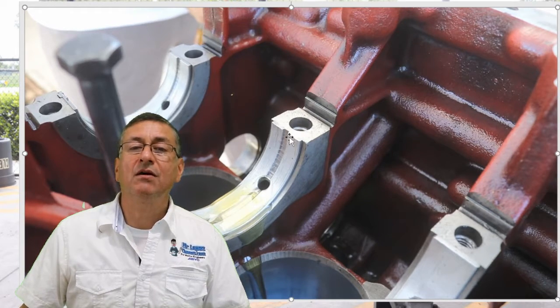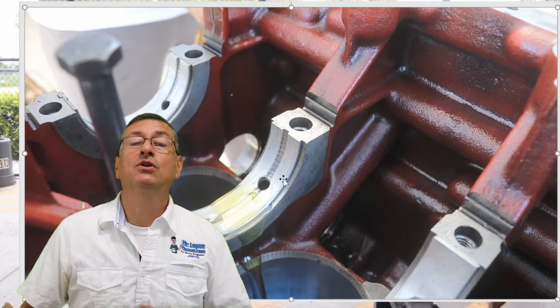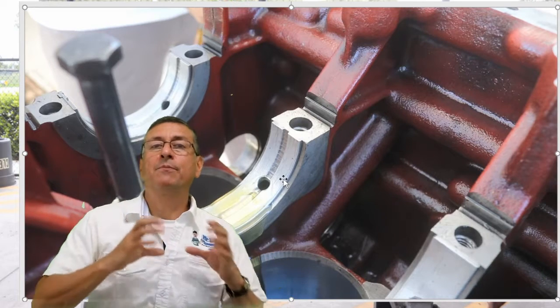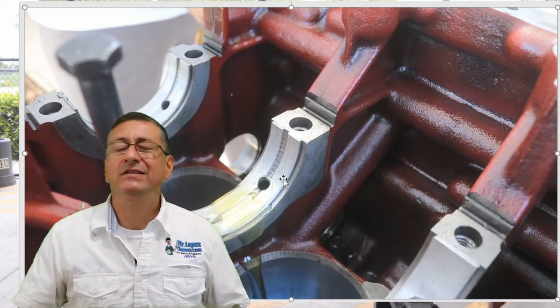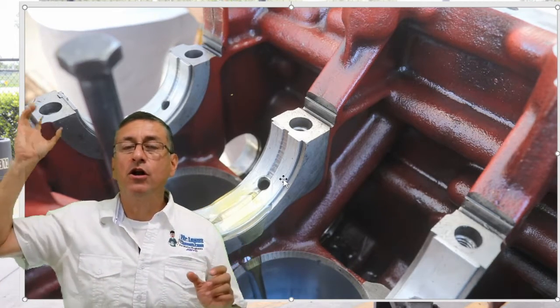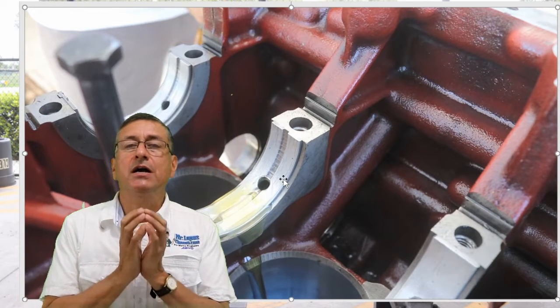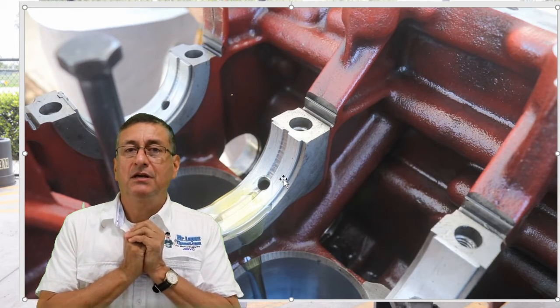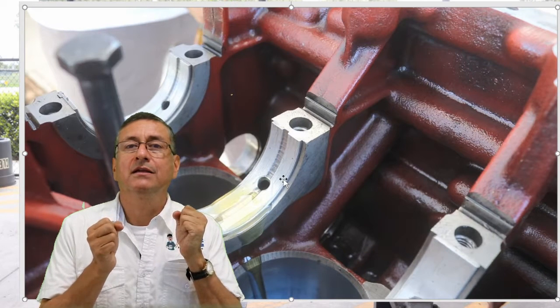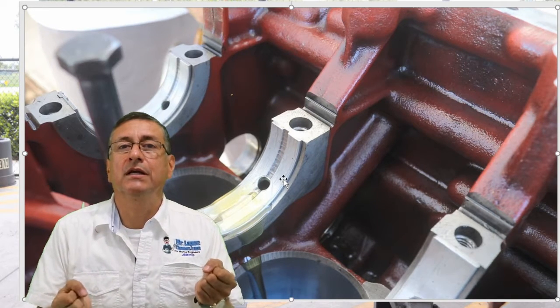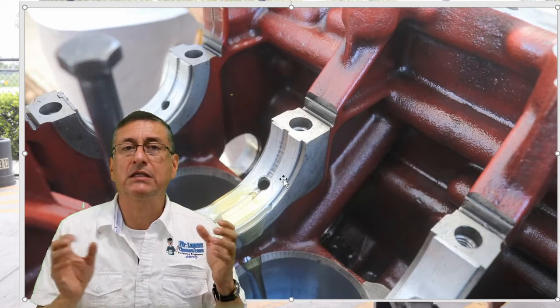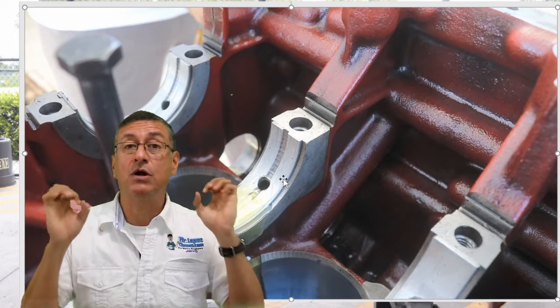Now you understand how important those holes are, because those holes communicate the oil and produce the pressure in the system. Once again, my friend, don't forget, the oil pressure gauge and the temperature gauge are the most important gauges. Those are the gauges that the driver, the captain, needs to check always, all the time, in order to verify the temperature and the pressure.